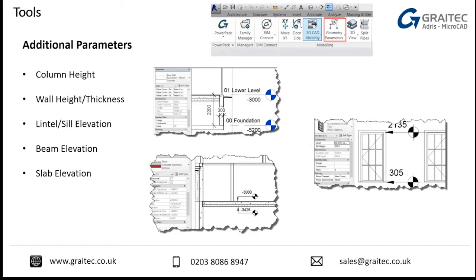We've added some additional parameters. Now, these are parameters that a lot of people have been asking for a while. These are additional parameters that are not only added to different types of families like columns and walls, but they're also schedulable. So we can start to schedule that information out. Something like column height has never been a value that we've been able to pull out. Now we can. A wall height, wall thickness, etc.